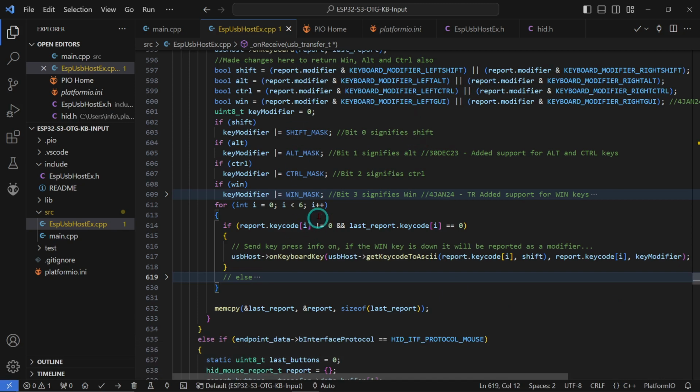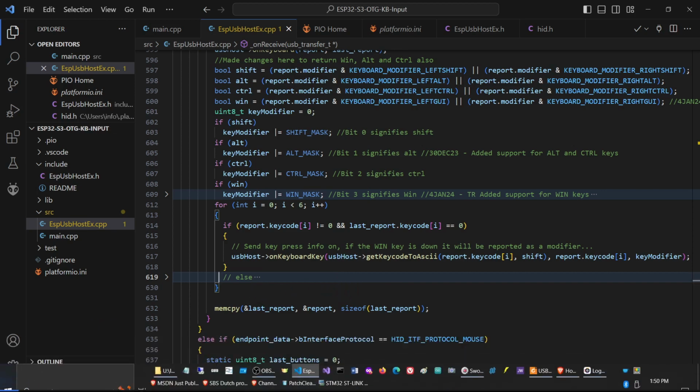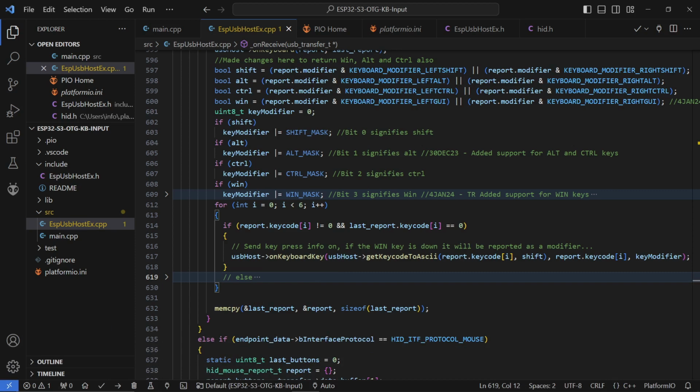So in any case, as I said, I need to look at this code. It is not right for what we're trying to do, because what I'm actually trying to achieve is that it reliably comes back with all the codes that are coming onto the USB bus for the keys whenever there is a change in keys, and then I can process those, and then I want to output the keystrokes again through Bluetooth, because unless I hook up another little USB board to it that can act as a device at the same time, because these controllers over here do not have two USB ports on them.